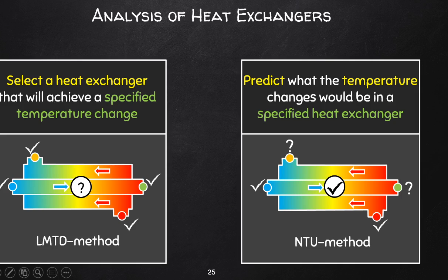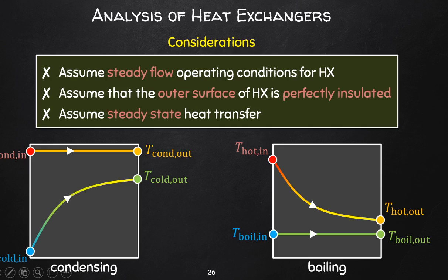Okay, so certain applications will not necessarily have temperature drops per se. Consider boiling, consider condensing, and note that only the latent heat is transferred to the fluid undergoing phase changes. So as the fluid enters and leaves, it is at the same temperature.